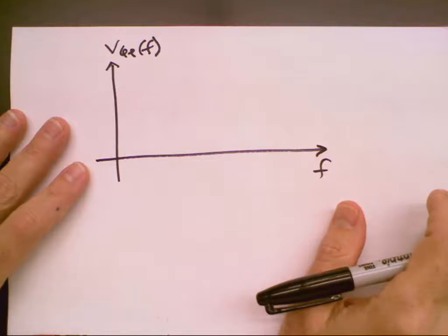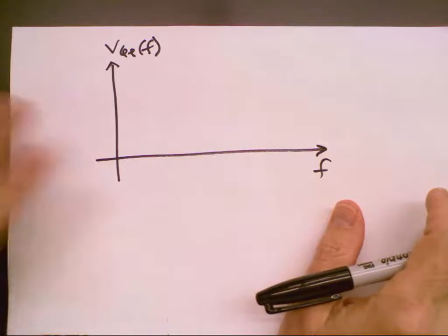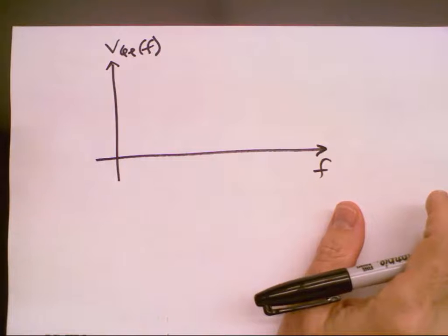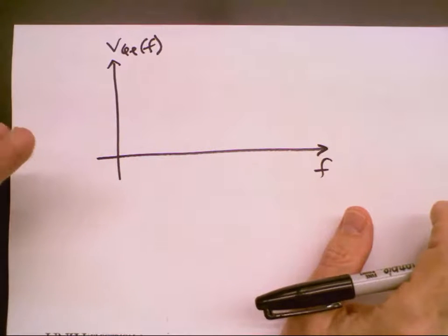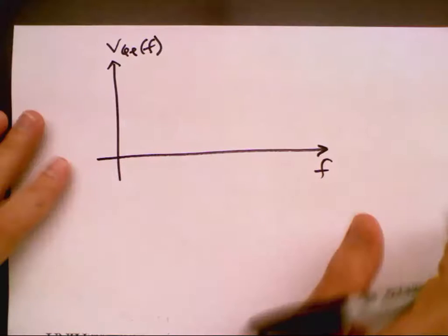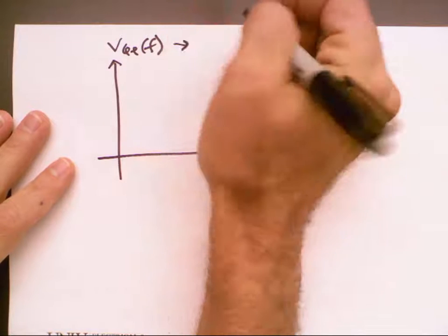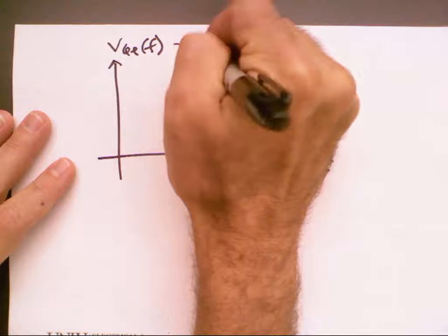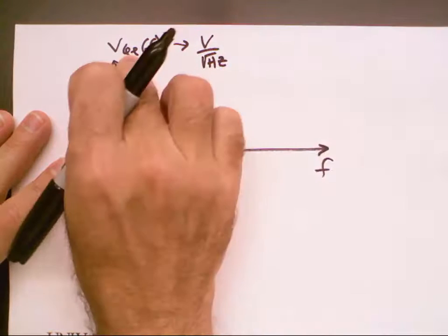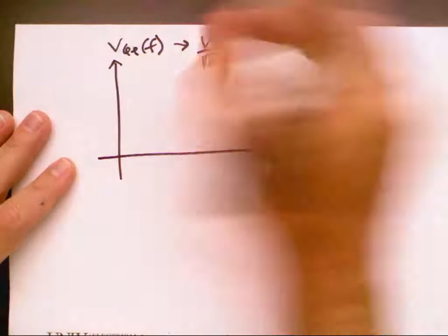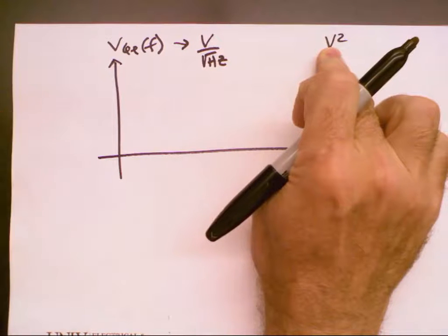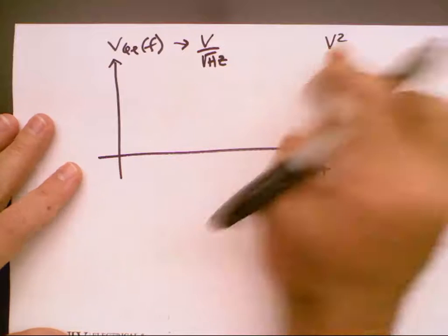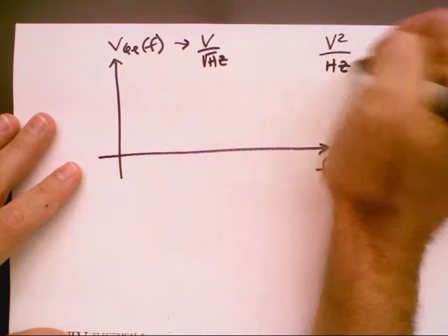If the units are funny, hopefully it'll make sense the way I explain it, but when we do advanced analog and we do noise theory, the units make a lot more sense. So the units here are volts per root hertz. And so what this is, when I measure the power in a signal, the power is normalized to a resistance, it's volts squared over some bandwidth.